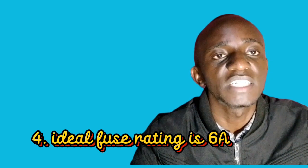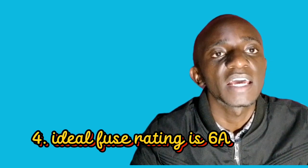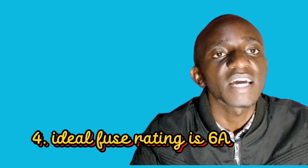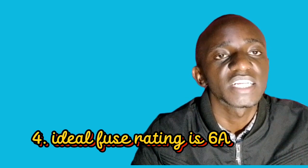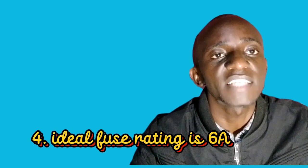So another IE regulation, the 4th one, is that the fuse rating for the switchgear, which is acting as a means of excess current protection, the ideal size should be 6 amperes, but practically we use 5 amperes because that is what most of the manufacturers manufacture. So those are the IE regulations that should be observed when you are doing a lighting circuit.